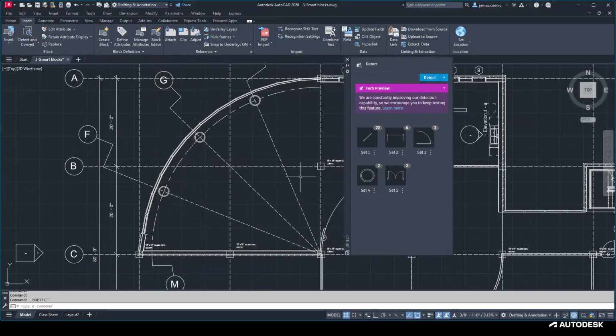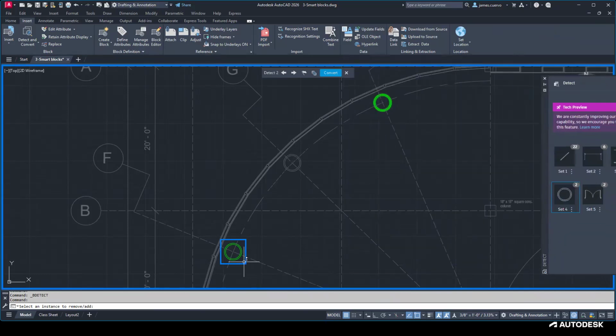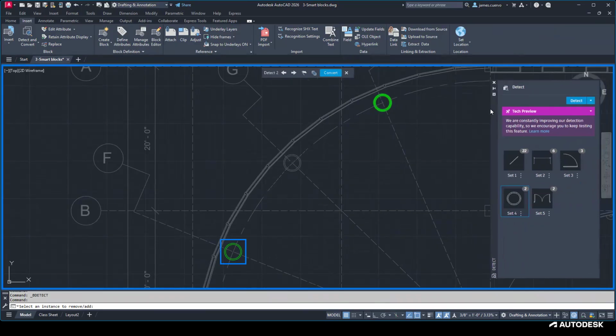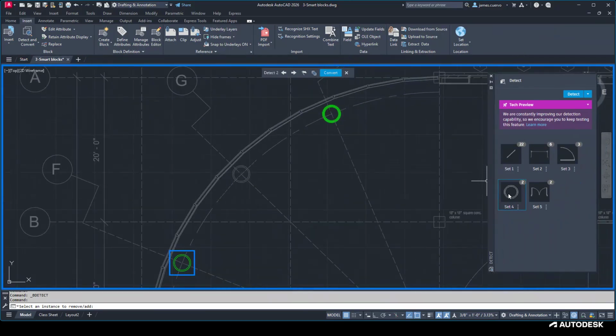There are three. So if we select the object and set the settings here, look what happens. It's selecting the two. There's a third one. It hasn't selected it. There's also a little tab up here that should look very familiar to you. This kind of looks like the XREF compare and drawing compare dialog boxes that we've seen before, which have been introduced slowly but surely into the AutoCAD environment. If we go ahead and say convert here, we can convert these into whatever it is. You will also notice that it's selecting these lines, and there are 22 of those.